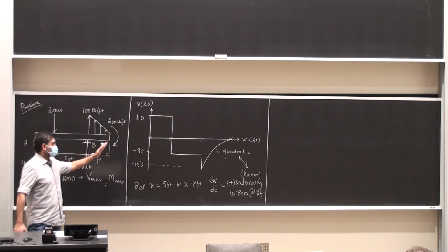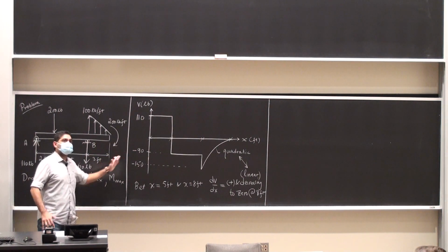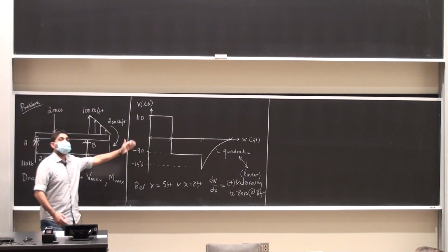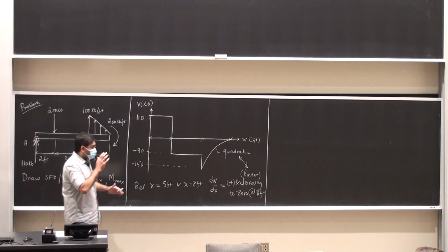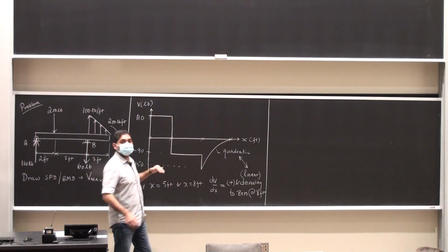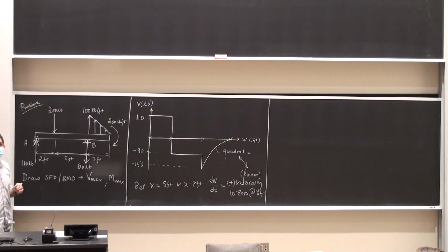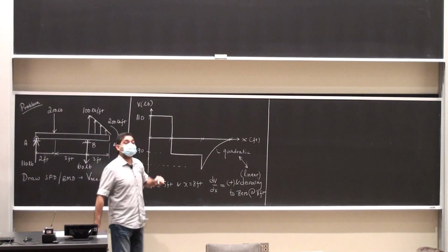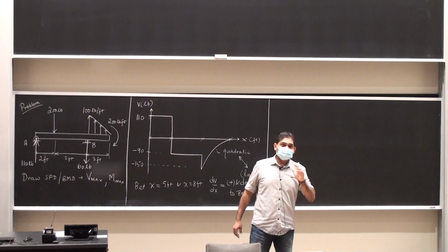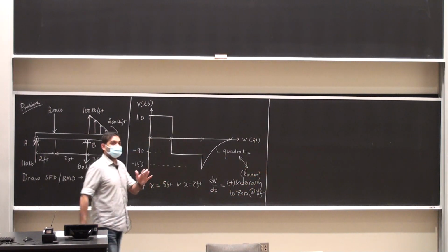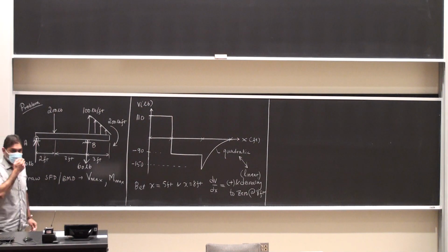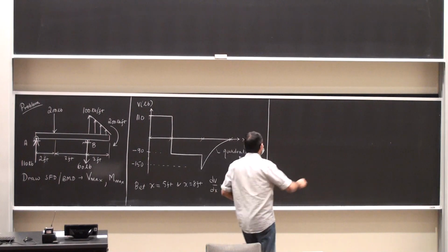It might be initially some growing pains, but once you distinguish, okay, there is nothing going on here. If I see a force pointing up or down, it's just a jump up or down. If I see a distributed load, it's going to change the nature of the curve. That's about it. And if I see a couple moment, it's not going to do anything to my shear force diagram. It has already done its duty. It has done its due diligence in helping us calculate the support reactions, so it would have had its effect on the calculation of those things. Okay? So we'll go to the bending moment and then we'll move on from there.